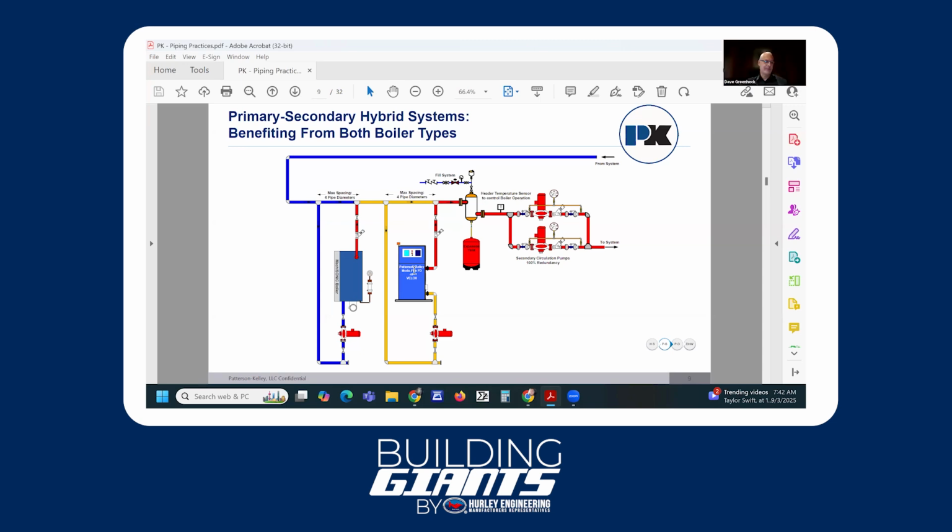Just by having a low mass boiler and better combustion equipment, we can gain certain efficiencies. But the big jump in efficiency in boilers is capturing that latent heat, and that only happens when you get below the dew point and start condensing the moisture in the flue gas. So ideally, too, we'd like that to happen inside the heat exchanger, right? It could happen right at the outlet. It could happen in the stack, depending on where you get to that point and you're below the dew point.